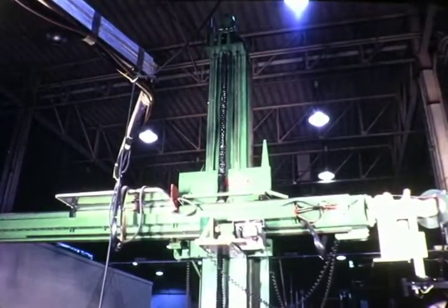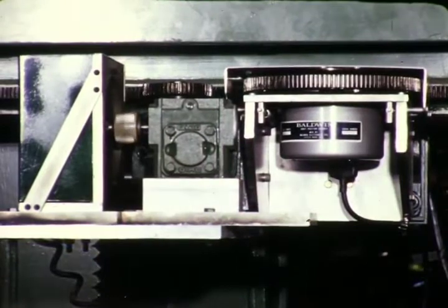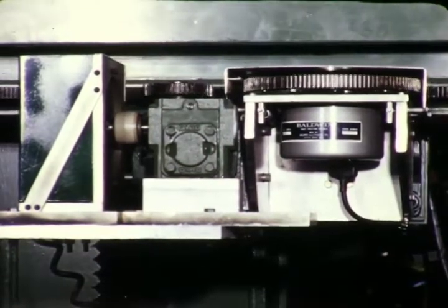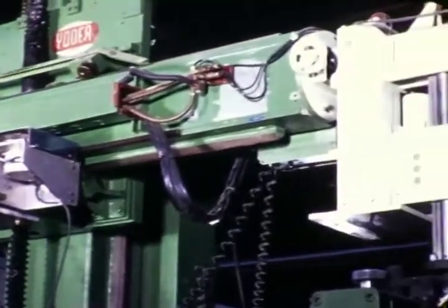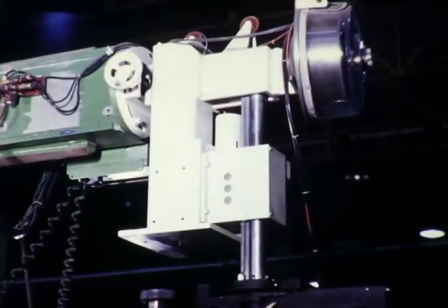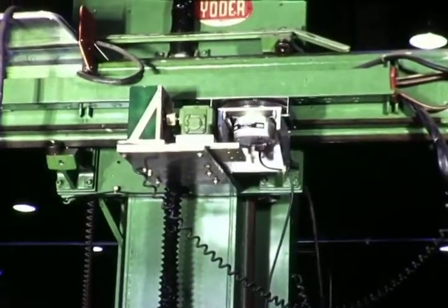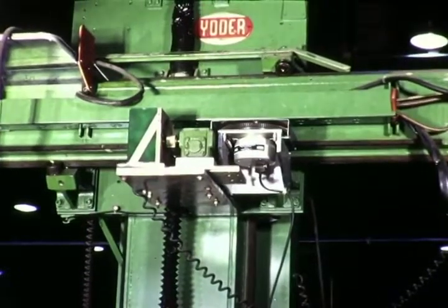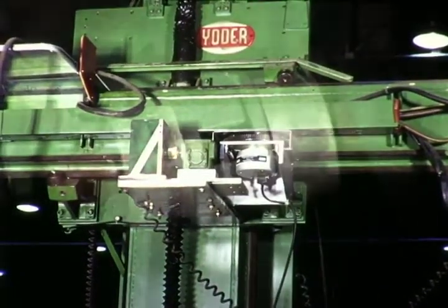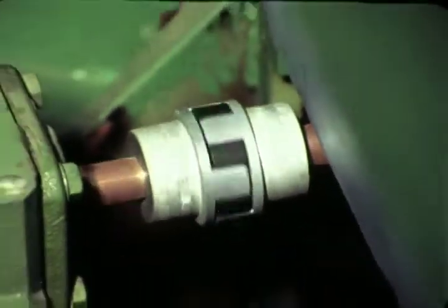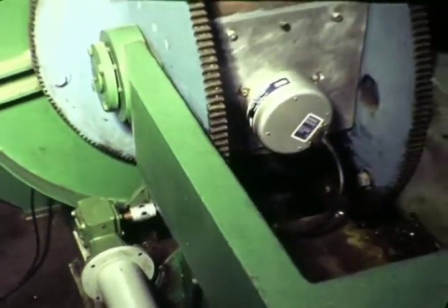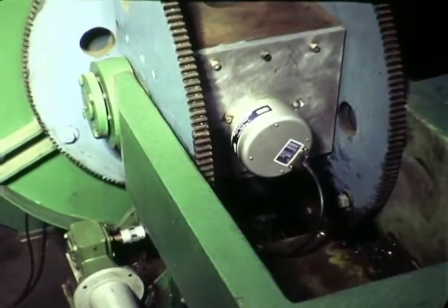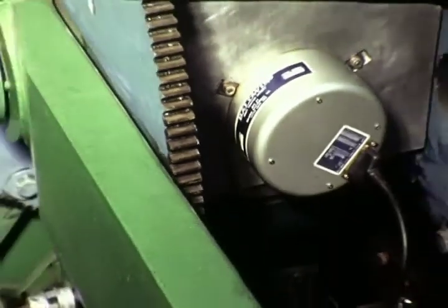The three main axes of motion controlled by the computer are the ram drive, which translates the welding torch horizontally, a vertical motion to assist the voltage-controlled torch head, and the turntable of a welding positioner. Note the direct-mounted absolute shaft encoder, which provides true position data feedback to the computer.